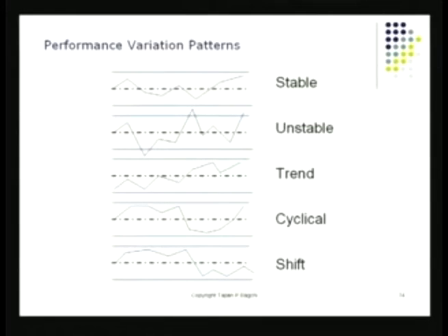Now, what happens after you plot the chart? You find some unusual patterns. One very simple signal that you get out of a process is that one of those data points went beyond the control limit. That's one signal out of a control chart. It can happen on an X bar chart, it can also happen on an R chart. Both of those charts can give a signal. What we have to do is see, can I get more signals out of the same chart? I need not really wait till I get a point beyond control limits.